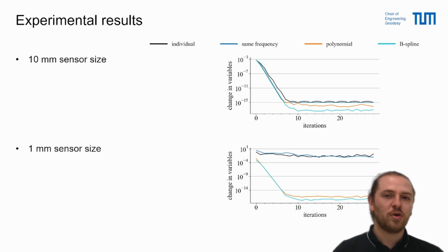Essentially, this method exploits the sampling rate of LiDAR in both space and time. It allows us to use spatial proximity to implement spatiotemporal connections, giving us a contactless, time-synchronized way to evaluate vibrations of entire surfaces rather than just single points.